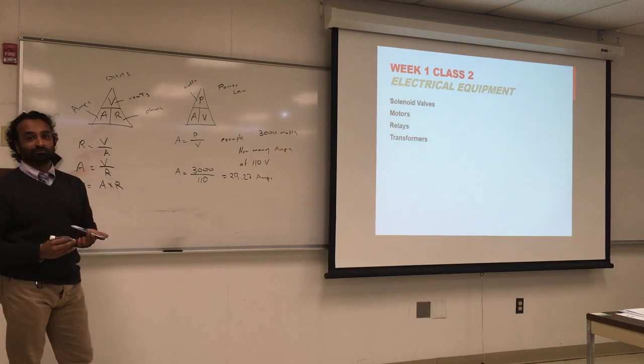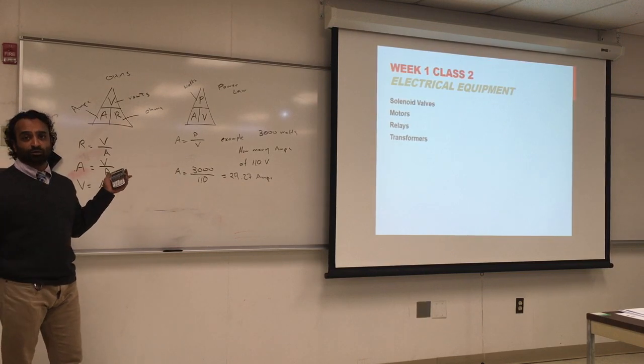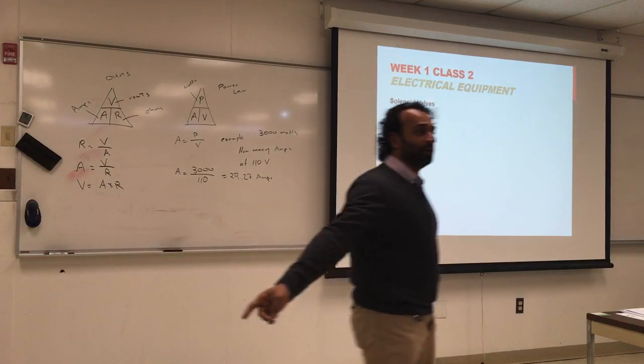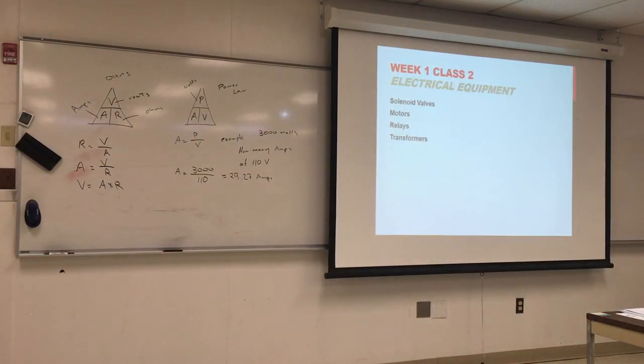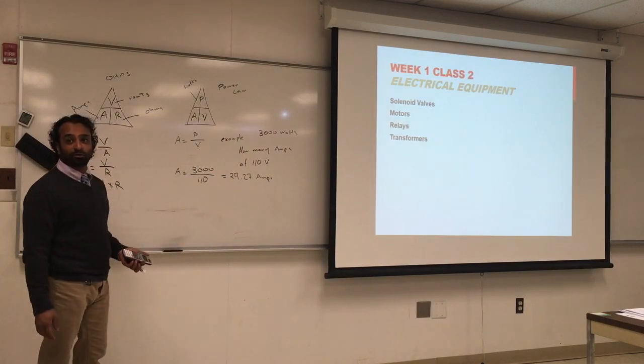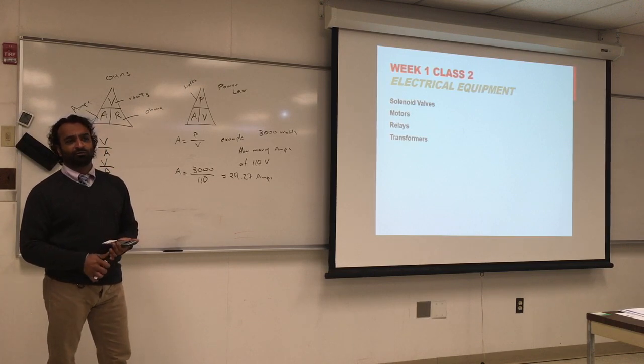Is that acceptable? No. If you're going to have equipment that draws this much, it will have its own circuit breaker, and probably you're going to go with 30 amps. And we do have some of those. We have 20 here, this is 50 amps, and it's 100 amps. So you've got to get a circuit breaker especially for that equipment and put it in the control panel. Examples: the clothes dryer, washer, some dishwashers, and an industrial size microwave will probably have its own circuit breaker.